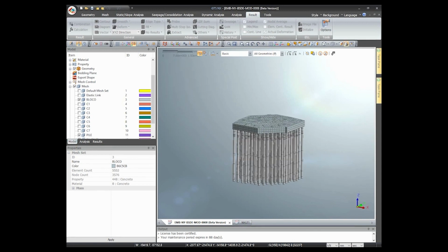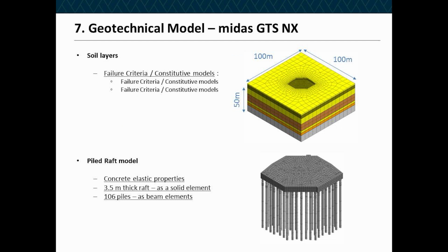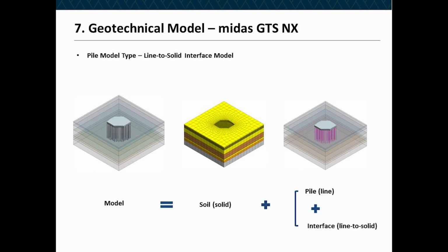So let's go back to PowerPoint. For the pile model type, there are some ways to work with piles in numerical models. And the best way would be to consider all piles as solids and define the interface properties and simulate its behavior. Well, the problem is that the model becomes way too heavy to compute.